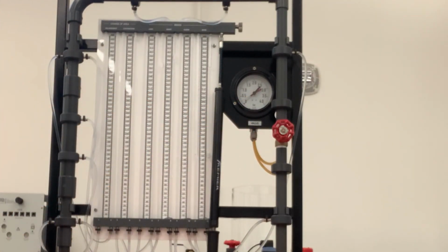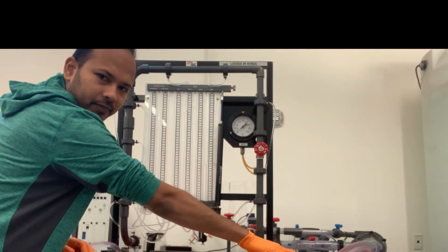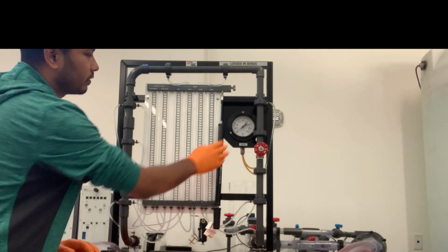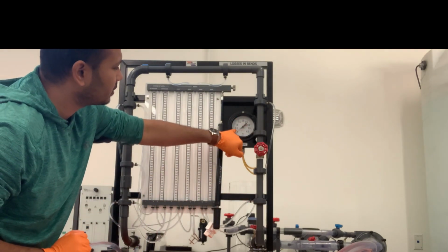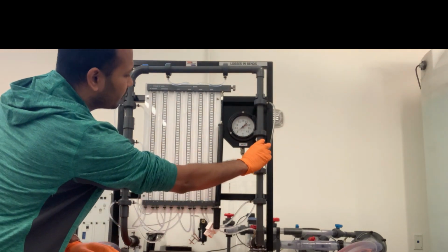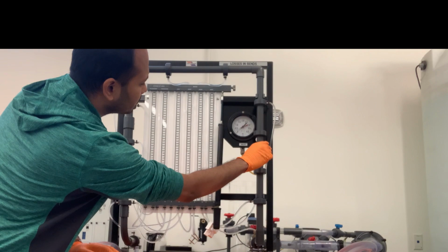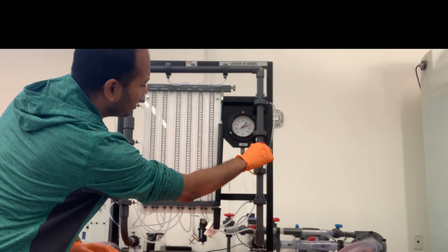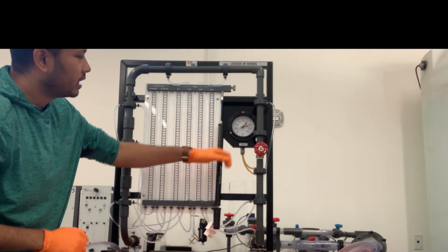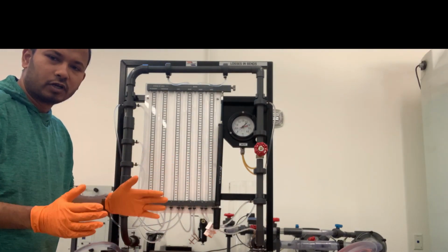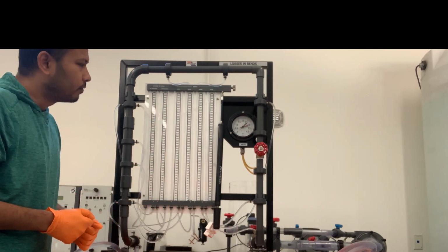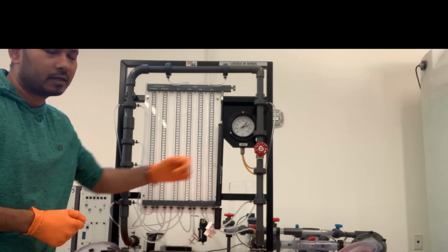Now what I can do is close this valve again and record the water volume given a certain time, so we can know the flow rate, and the head loss would be 0.2. Again, you have to repeat the data, closing further. So now I'm at about 0.4. Again, at this position, you have to take the reading, how much water volume is collected in a certain time, and this is how we collect the data for the gate valve minor head loss.